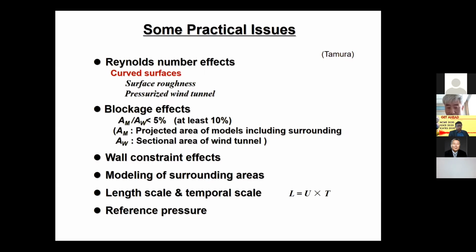Prof. Thomas just introduced that we have to model surrounding areas. And also we have to consider length scale and temporal scale, because we scaled down our model already. So the real 10-minute phenomenon and the one in the wind tunnel at that scale are different. We have to consider the relation of length scale and time scale. Of course, we have to pay attention to the reference pressures.